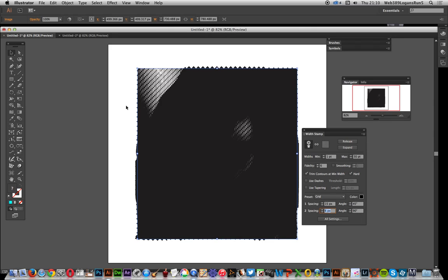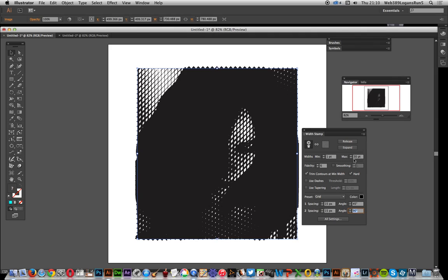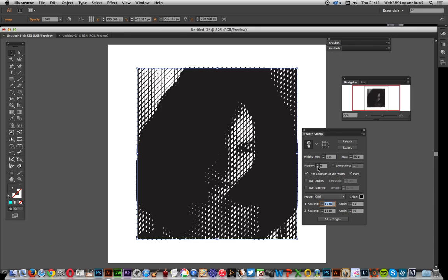and you can see it's now angled at 45 degrees. And I'm going to increase the setting again. It's just a bit too much, so that's 15. And maybe make that 20. Now you can modify the fidelity, which makes it rougher or smoother. Obviously it adds more slowness, because it makes a more intense, more complicated path. High fidelity results in more closely spaced width markers, which you might want, but on my machine, which is not the quickest of machines, it's probably best to keep it fairly low, but it makes the image slightly rougher. Anyway, I'm just going to go with that.